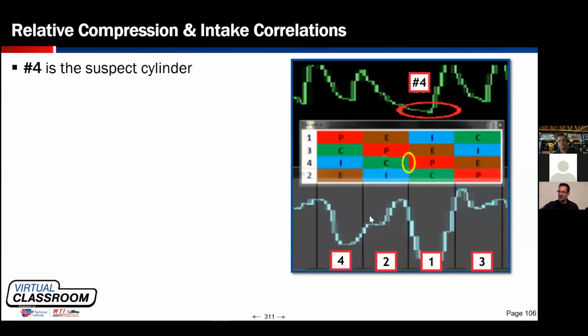Bryn, I don't know about you. Do you see a pull? No, I see it kind of plateau, yeah, for a second. Yeah, but it kind of plateaus, but then I kind of see a what? I kind of see a push. Yeah. Right? Not a pull, but a push. So let's think about this. If number 2 is supposed to be pulling on the intake manifold, like number 4 is, we think number 4 might have an intake valve sealing issue, according to this area right here. Everybody raised their hand, so I'm sure they're in agreement with me, just putting the puzzle pieces together.